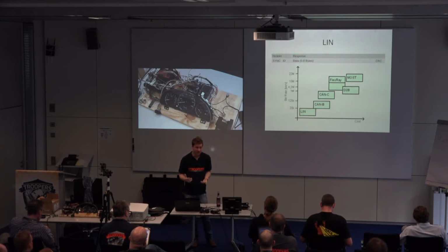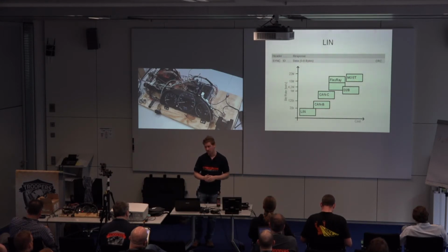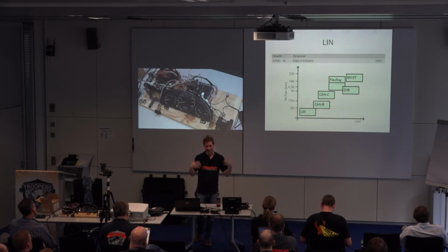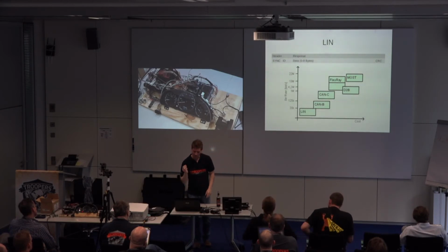One thing you will have to compete against is that the device that's supposed to be sending that signal still is. So typically the way that works is you just want to be more chatty than that guy. Or talk directly after him would be the better way to do it. So if he says your speed's 60 miles per hour and you want to make it 90, you can either wait for him to say 60 and immediately go 90, and then it'll automatically update to 90. Or you can just keep yelling 90 as much as you want, and then it'll mainly show up as 90. You'll just get one packet every so often that'll look like noise dropping it.